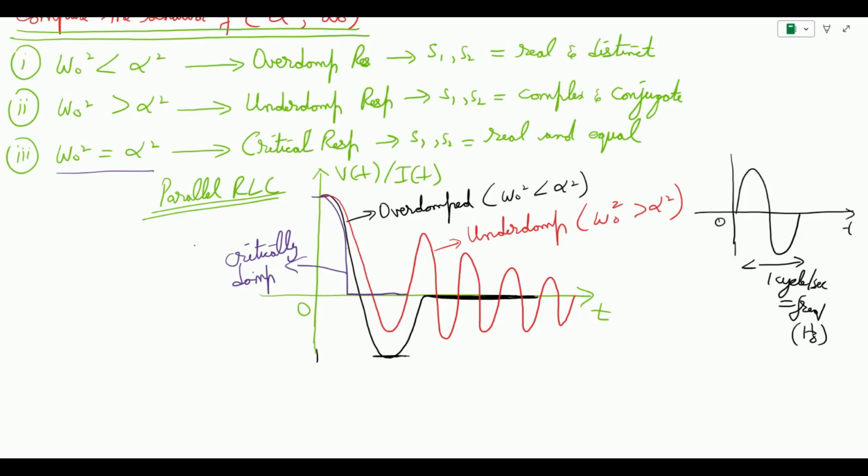So this is the behavior of the waves or sinusoids when we are dealing with RLC circuits, keeping in mind that LC will make your circuit resonate until it fades out, and R acts as a damping value and tries to bring the resonance quicker to the steady state before the whole of the energy is released. So this is how RLC circuits behave, and this is the way to represent them in terms of the Neper frequency and the resonant frequency.